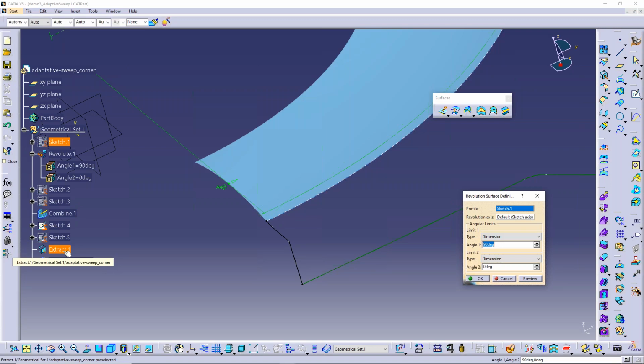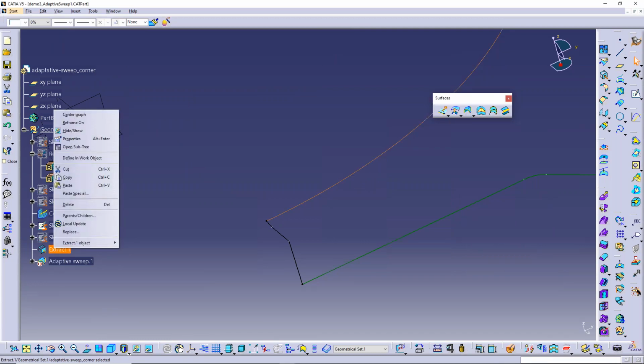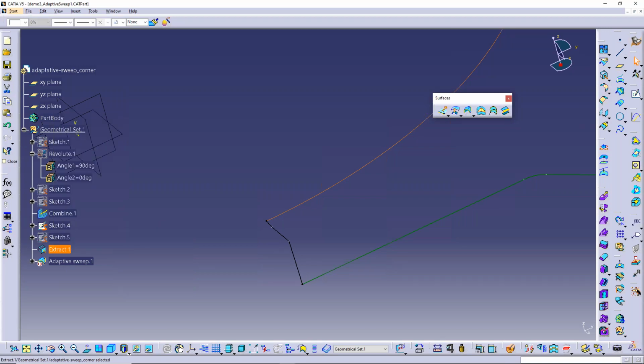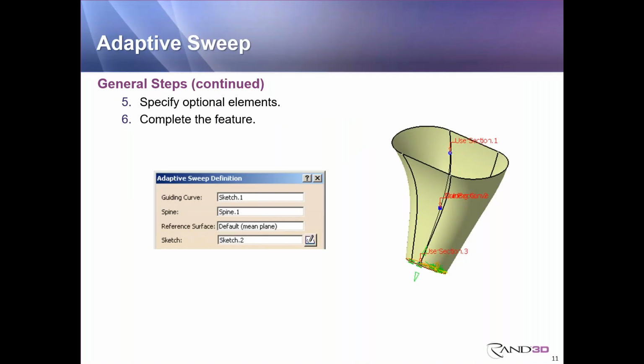And sometimes if you run into issues and you've already created some type of extracted boundary, those can be isolated. You can come in to an extract or boundary independent feature, and you can choose to isolate it as an independent structure. That will detach it from the parent surface, and that might be enough to avoid gaps in the surface, right? And that's a better quality in most cases. That's something to think about, because remember, that's going to separate it from its parent source. But if that's what it takes to change the quality to what you need, then it's an option. We're only talking about options here.